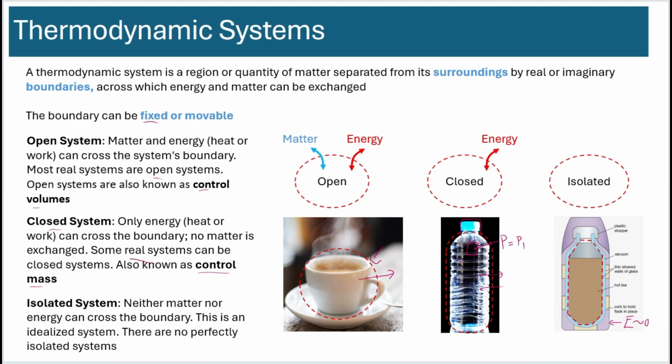If you took a bigger, larger size within the same system, the pressure is still P1. Same thing goes for temperature, T1, T1. I'm assuming that it's already in steady state, so there's no temperature difference within this. Such properties that don't get affected by the size or the number of molecules within the boundary of the system are called intensive properties.